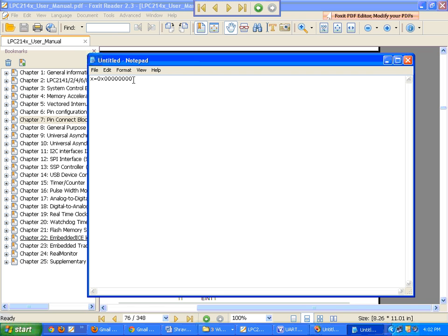So totally there are 8. These are called nibbles. Each nibble consists of 4 bits. So how many bits is that? 32 bits. That is the representation of any register in ARM. Okay, so you have to club the 32 bits. What value comes for the first 4 bits, what value comes for the next 4 bits. Based on that you will write the hex value. This is clear?